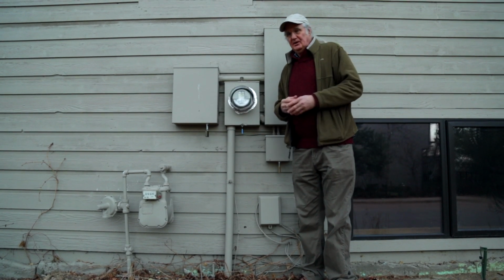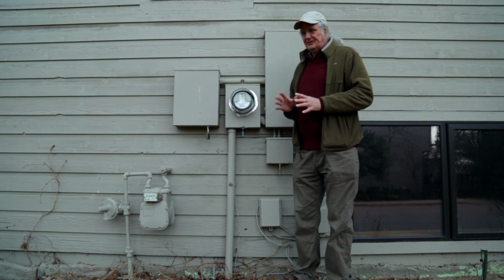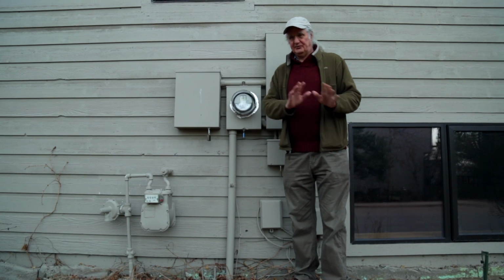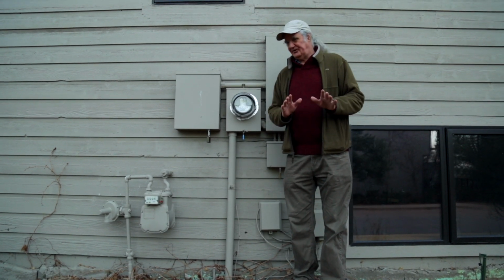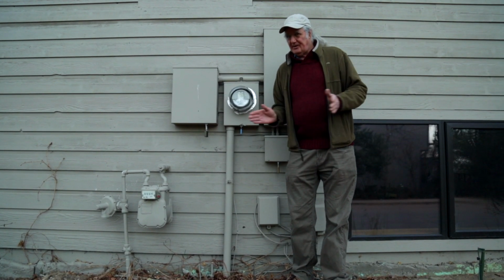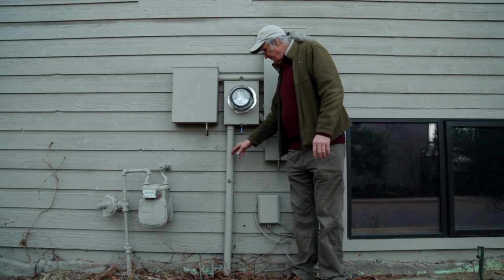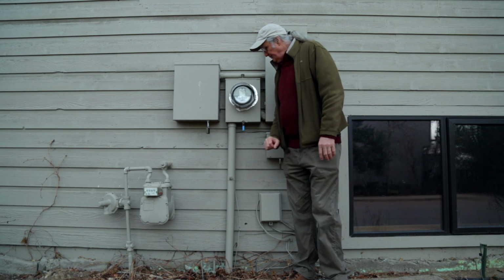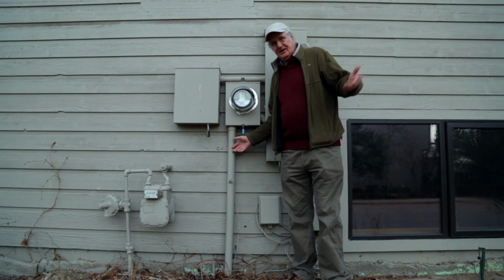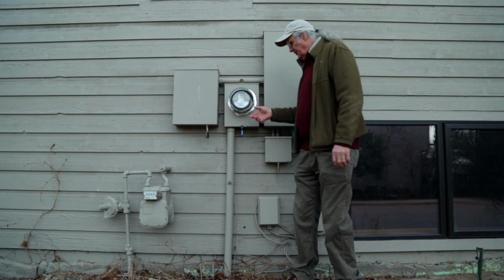But if you give electricity another way to get back to the transformer, it will take that as well. So electricity does not take the path of least resistance exclusively. It takes the path of least resistance primarily. But if you give it a parallel path, like water flowing down a mountain, it will take all paths. So maybe 85 to 90% is here, and you can have 5%, 8% or so going on these other paths.